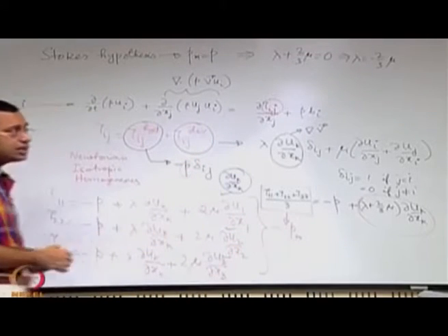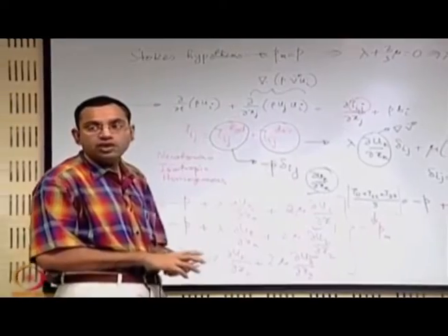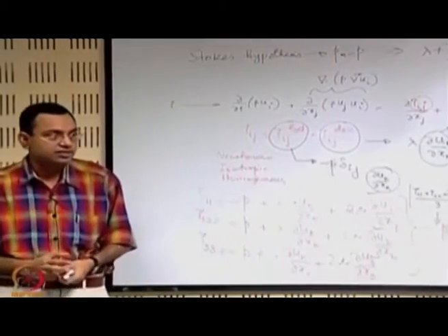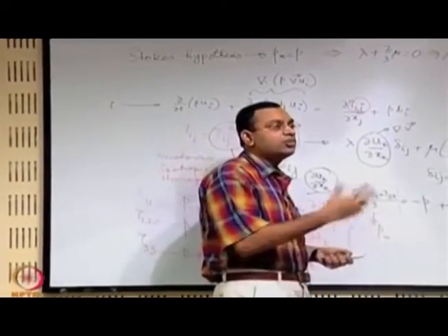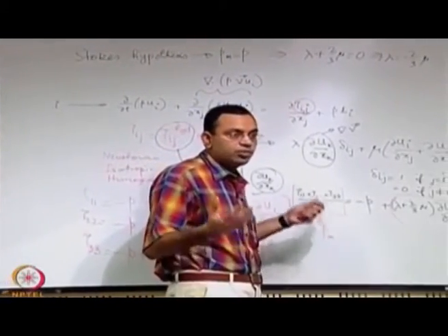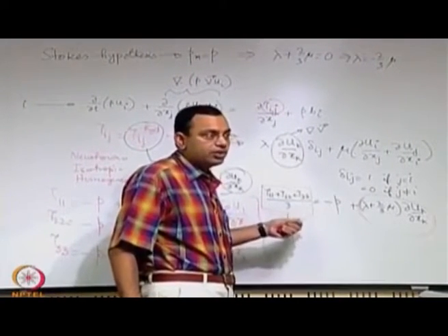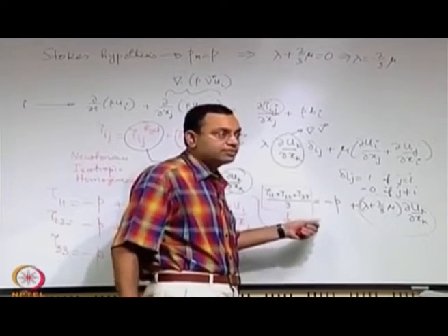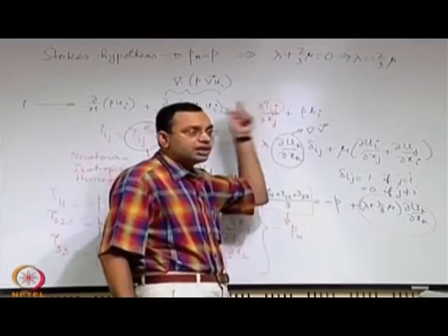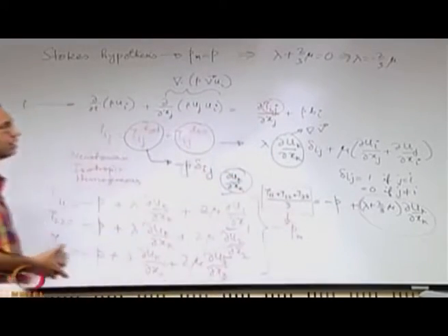But there are certain cases when you will not have a rotational and vibrational mode of energy, you have purely translational mode of energy. Think of a dilute monoatomic gas. There, the translational mode of energy is the only mode of energy, even when you look into it thermodynamically. So in that case you do not have any distinction between mechanical pressure and thermodynamic pressure, and then Stokes hypothesis is not a hypothesis, it is an exact reality, there is no deviation.